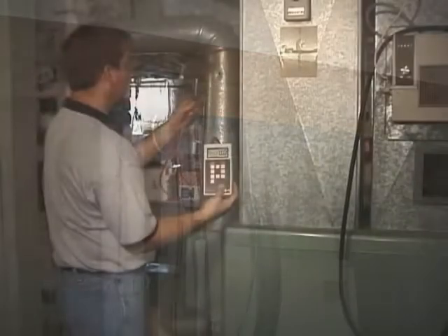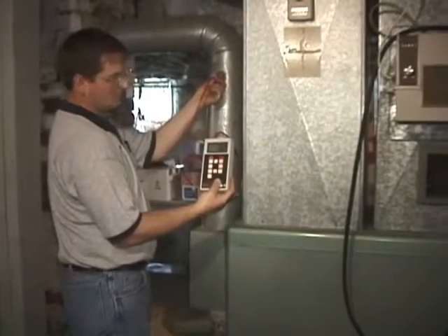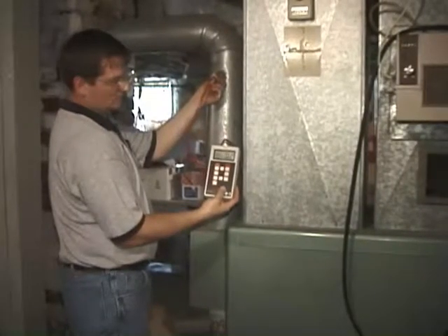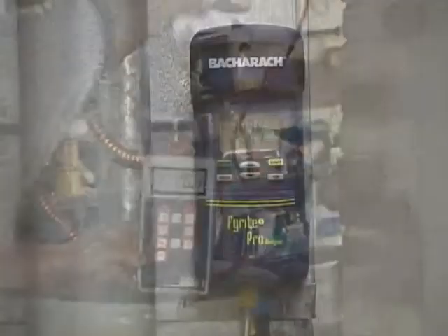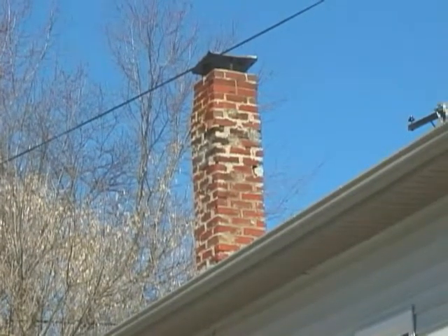As we reviewed earlier, Category 1 appliances must be connected to a properly sized vent, not too big and not too small. When a water heater is left connected to the existing vent that used to serve both the water heater and a furnace, we often see very weak draft, continuous spillage, CO production, condensation in the vent, and dangerous deterioration of the vent caused by the acidic condensation and freeze-thaw cycles.